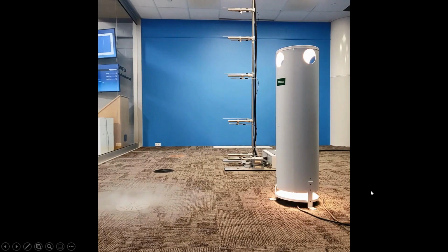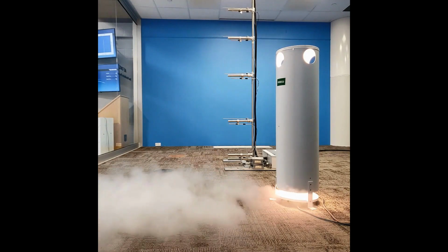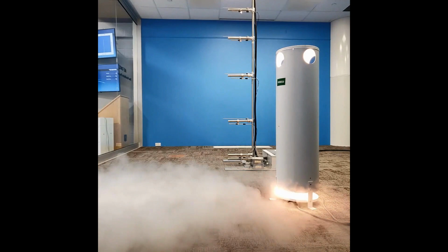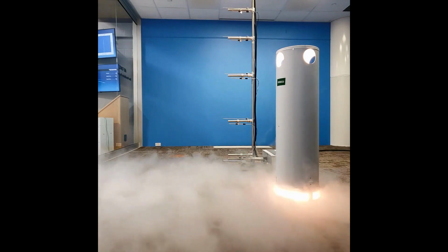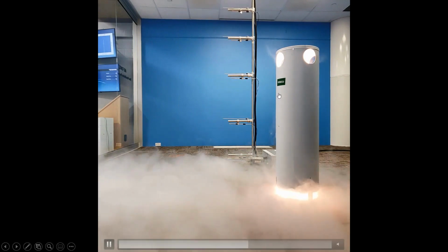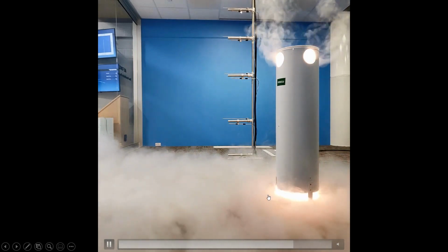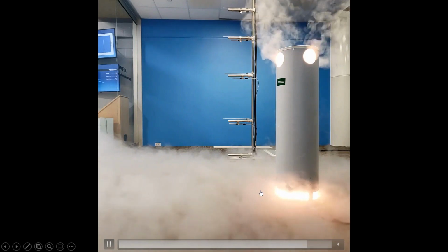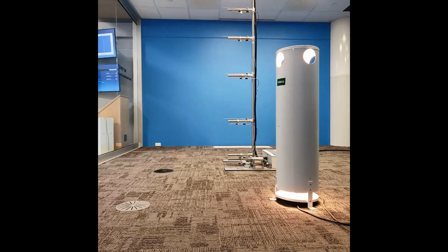So in terms of the different diffusers and approaches that you can take with an underfloor air system, this is a fully stratified displacement round floor diffuser. What I would say with this one is this is really going to maximize your stratification. You'll see the smoke plume is operating just like you would have with an in-wall displacement approach. And the nice thing with these is you could put them in conference rooms or private offices, directly underneath desks.